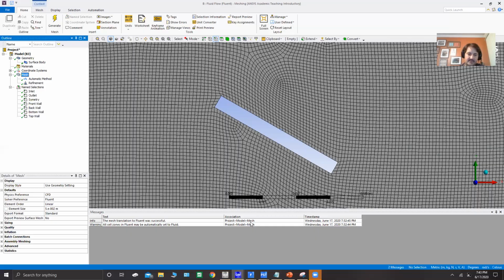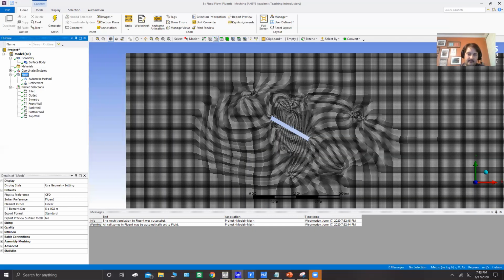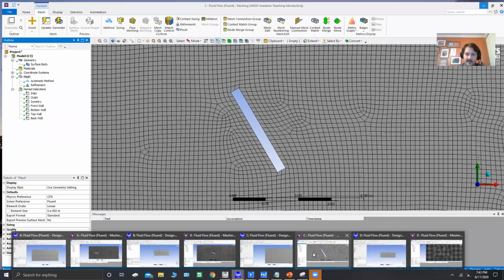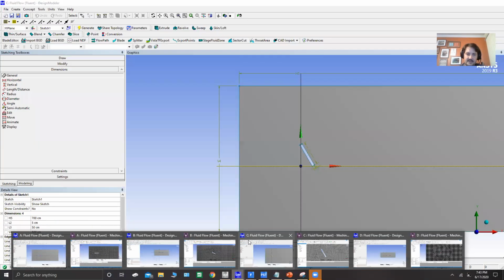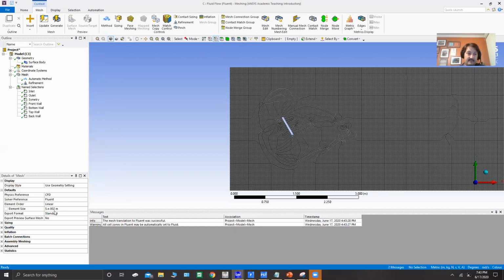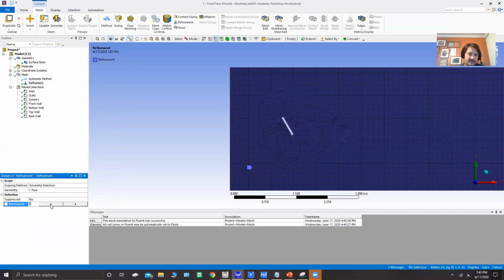Once the mesh was generated, we go to Fluent here. You know what, that was the wrong one because we're talking about 60 degree here. So this is your 60 degree mesh here. I apologize. So you can see it, 5 centimeter or 0.05, right? Our refinement, didn't do 3 here again. All right, so we'll run another simulation. Yeah, update. Cool.